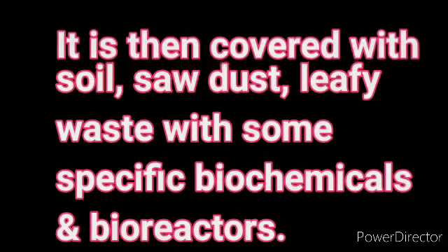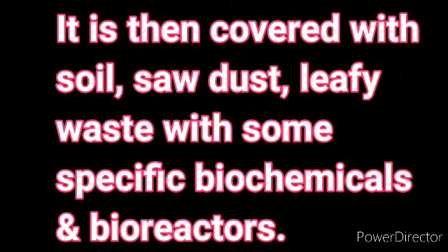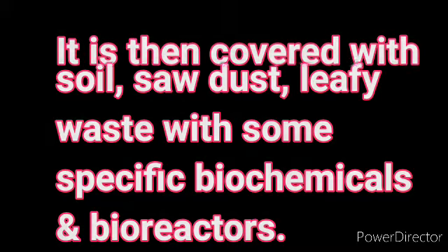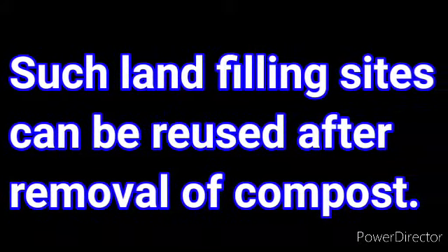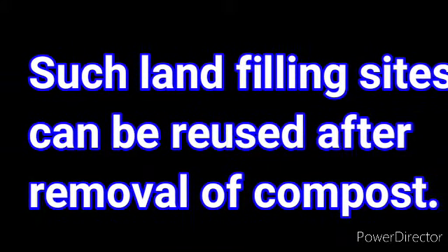Compressed waste is dumped in the pit. It is then covered with soil, sawdust, leafy waste, which are added with some specific biochemicals and bioreactors. Completely filled pits are sealed with soil slurry. Best quality compost is formed after few days. Such landfilling sites can be reused after removal of the compost.